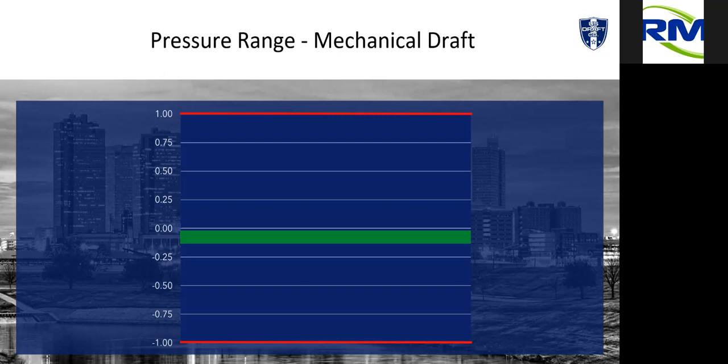But it's dependent on the CO2 level of the boiler. It's dependent on the efficiencies of the boiler. There's several things that go into it, but rule of thumb is the less efficient the appliance, the more CFM of exhaust that boiler will have. Reason being, you just have more excess air in your exhaust. So hopefully that's the quick answer. Zach, I'll let you go ahead and provide the longer answer in text form.